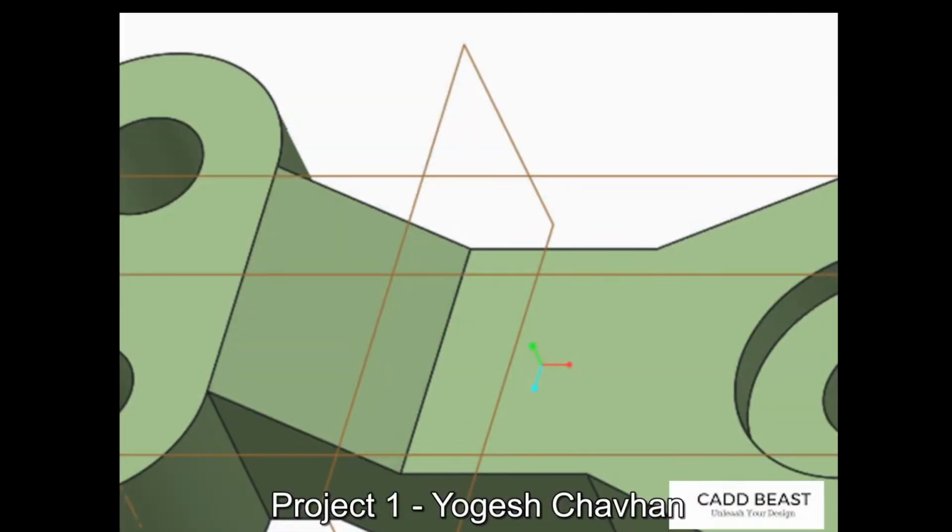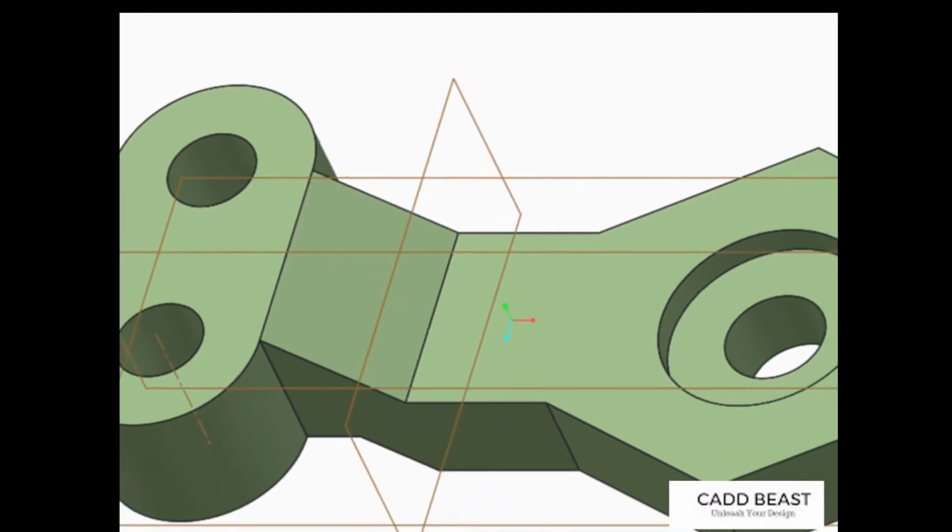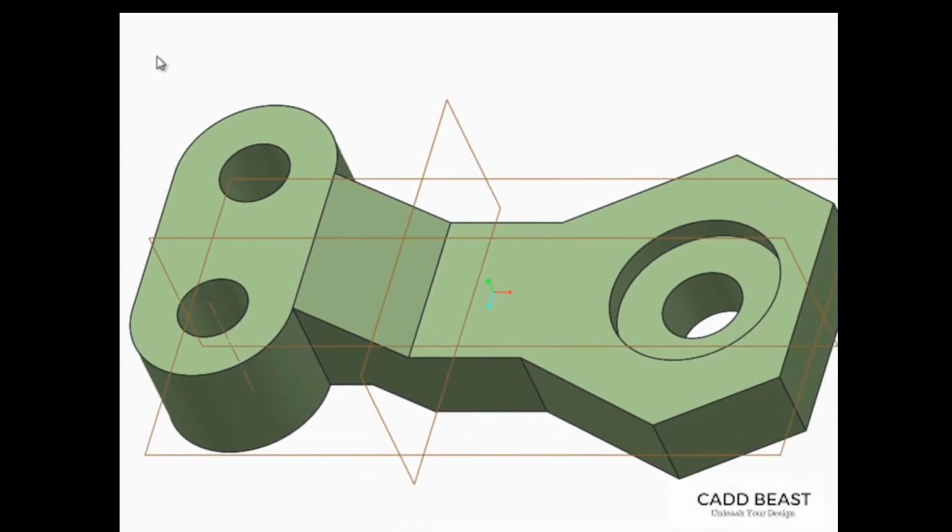Datum planes are 2D reference geometry. They have no mass and are infinite in size. In Creo Parametric, datum planes are typically used as construction geometry for features or as a reference when assembling components. The right, top, and front datum planes included in all the default template models are known as default datum planes. Every feature in a model is directly or indirectly created with reference to these three datum planes.